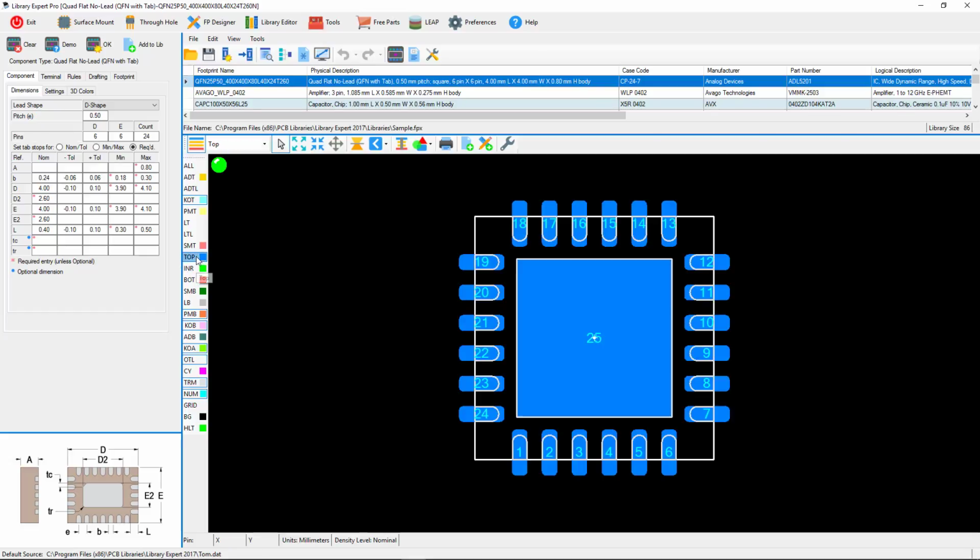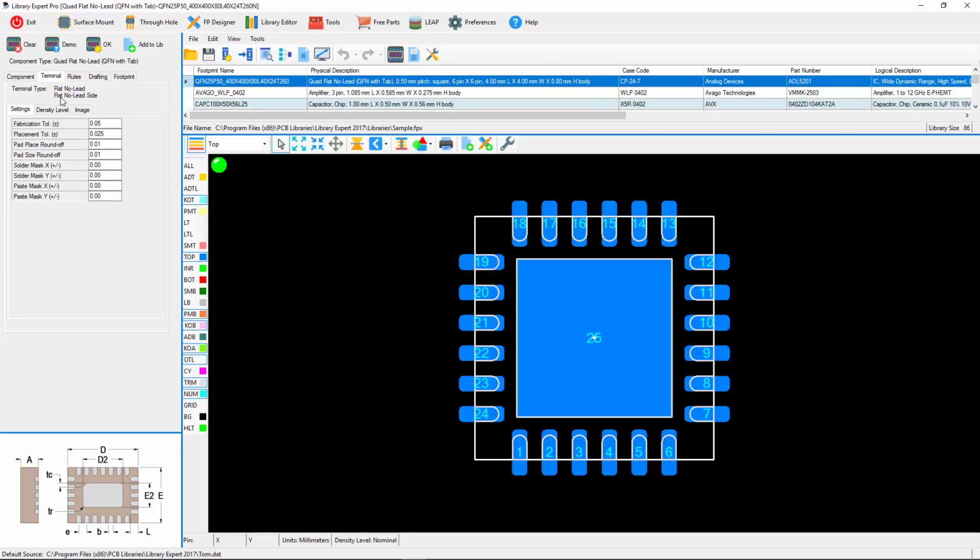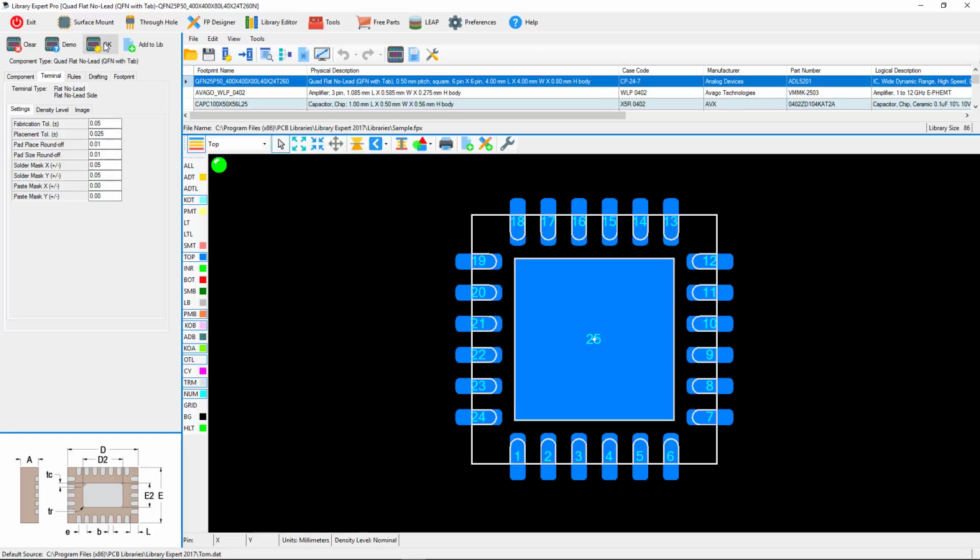If you turn on the top layer, you can see that the pads are placed by your rules, by your preference rules. You define the toe and the heel and the side. You define the solder mask. If we have solder mask swell and preferences, by the way, these preferences over in the panel here are primarily used by light users. The professional users will use the main preferences that are applied to all parts.